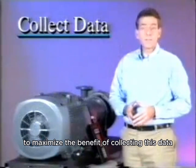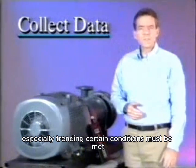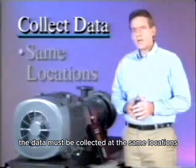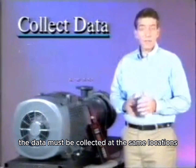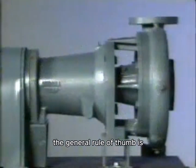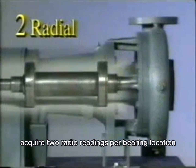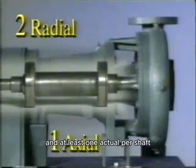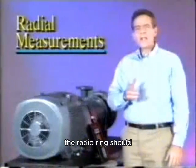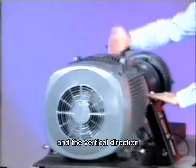To maximize the benefit of collecting this data, especially trending, certain conditions must be met. The data must be collected at the same locations, in the same way, using the same sensor type and the same sensor mounting. The general rule of thumb is, acquire 2 radial readings per bearing location, and at least 1 axial per shaft. The radial reading should typically be the horizontal direction and the vertical direction.